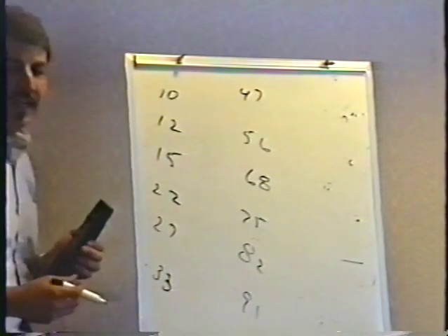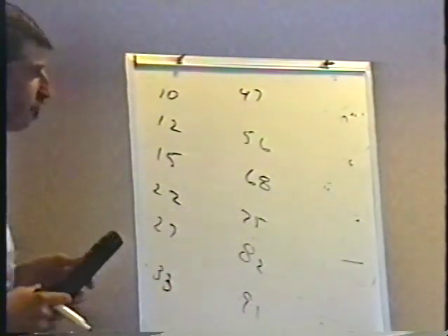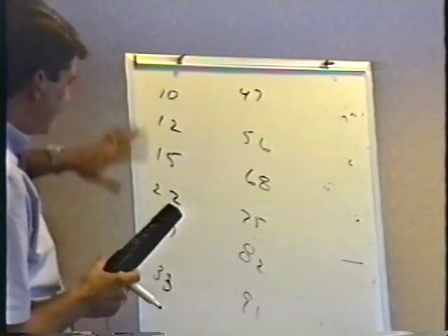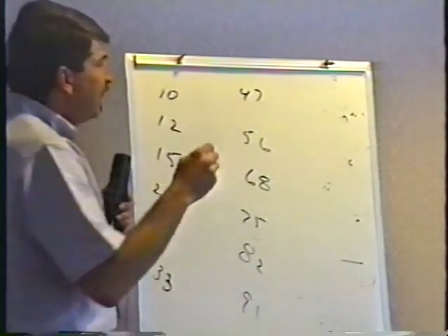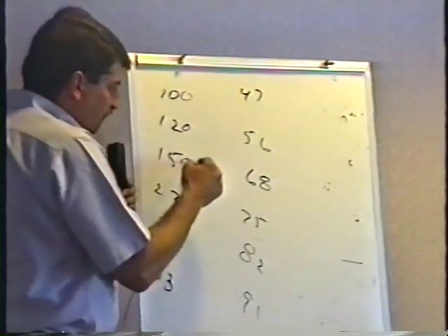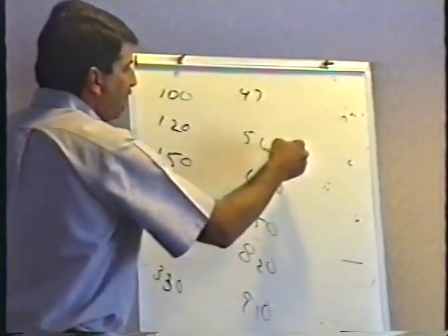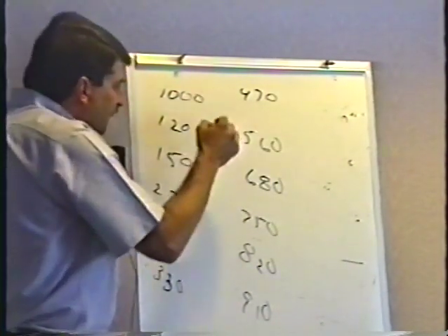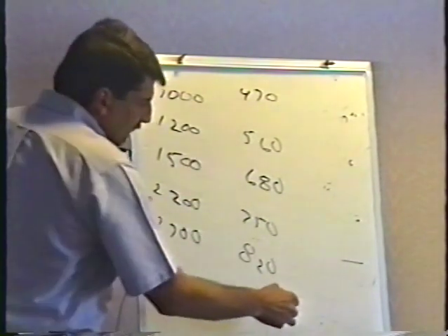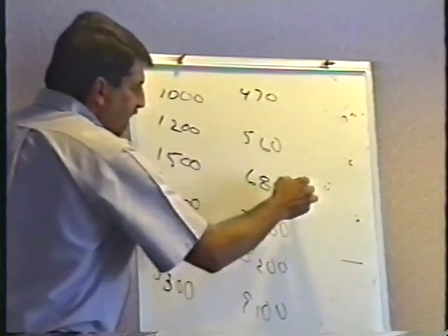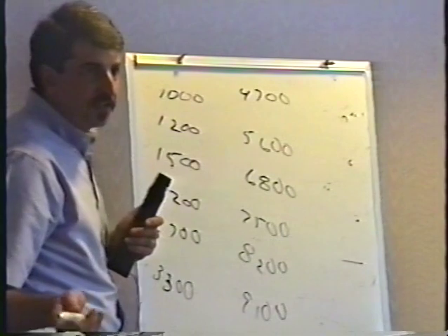But you don't see all the values. In other words, they don't really make some of the values. There's some, like they make 18 and stuff. But I see powers of 10. In other words, I see 100 ohms is common, 120, 150, 220, 270, and so on. These are all common values. So are these, 1,000, 1,200, 1,500, 2,200. What's changing here? Just the third band, huh? The multiplier is the only thing that's changing here.